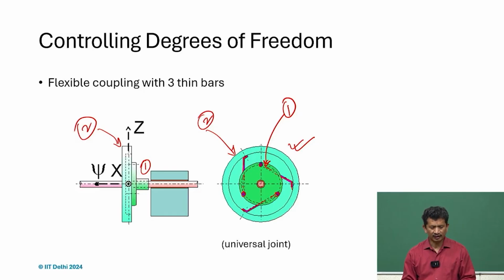And what is interesting and important to remember is, if we extend and drop a perpendicular, we should always find this, call it R. It should be away, it should not pass through the center. The moment it passes through the axis of rotation, we do not get that coupling effect or the required constraint. Although after some time it can rotate, since it is not constraining, only after some rotation can it provide that torsional moment, and then you can move, but the precise location is not possible.